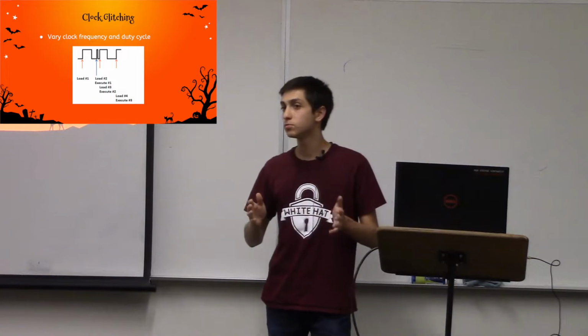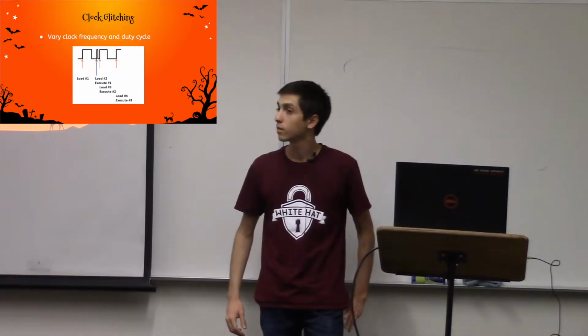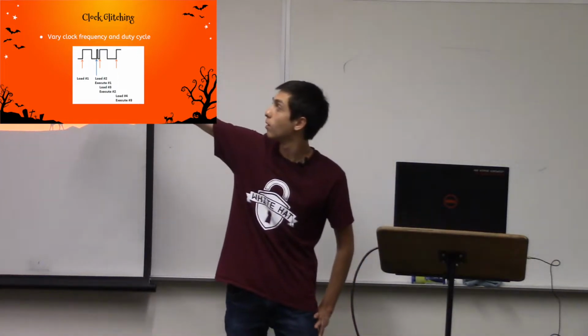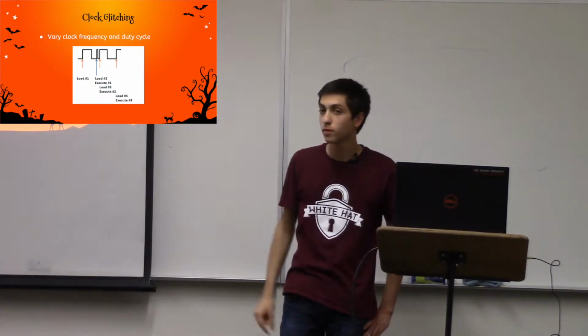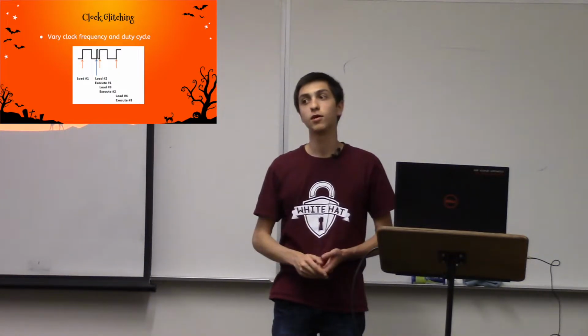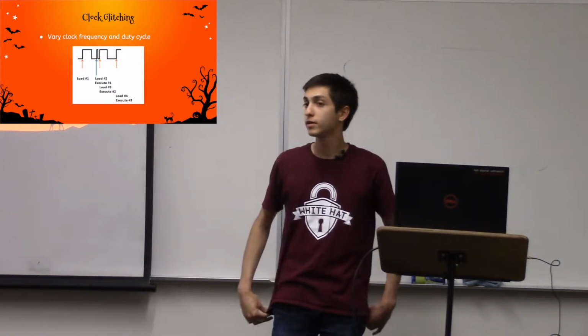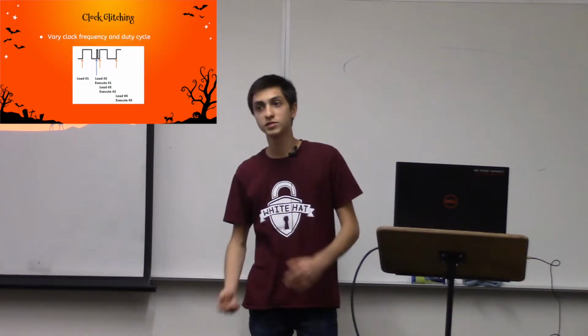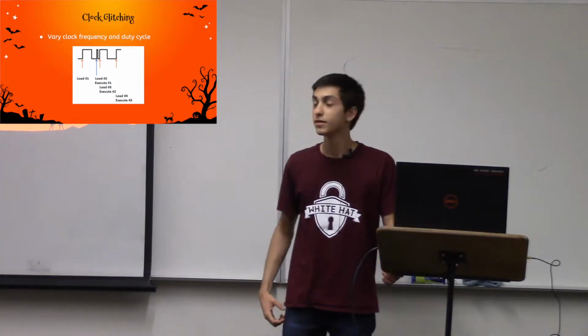So when the computer's trying to do that, we can introduce a clock glitch, which is like that little bump right there, the small one, where we change the frequency and make it really fast, faster than the hardware is expecting, and we can skip instructions in a program or cause the program to misbehave.